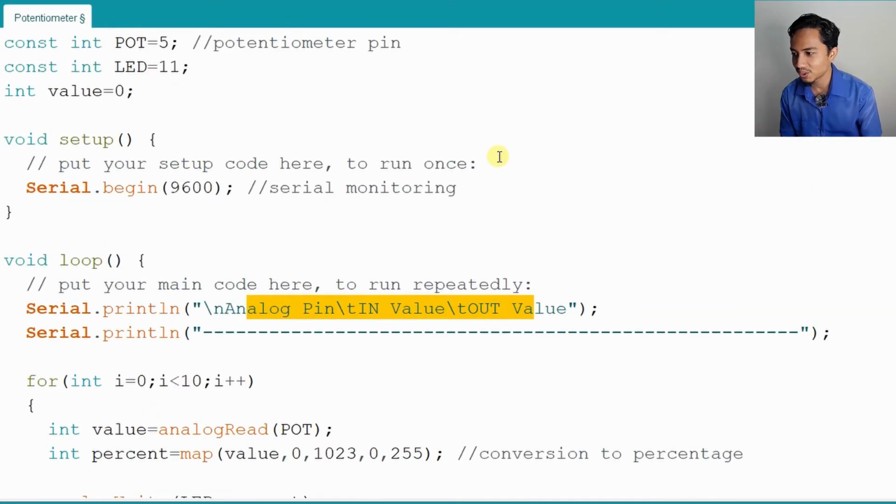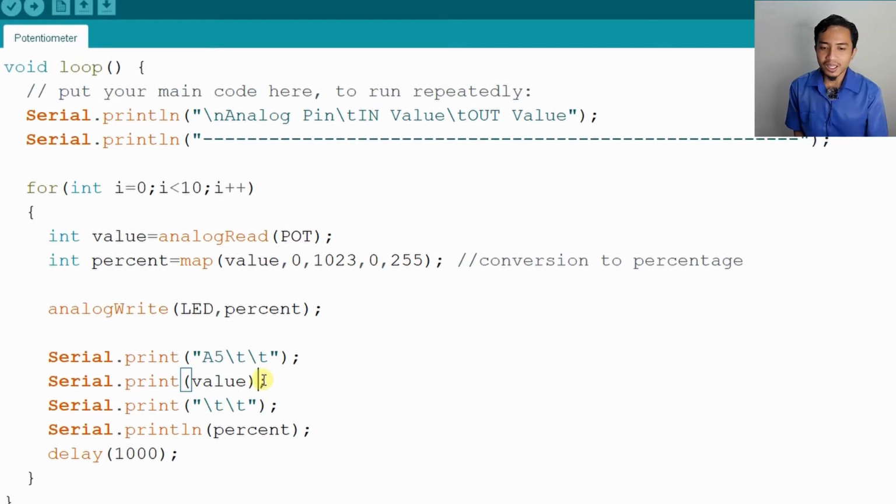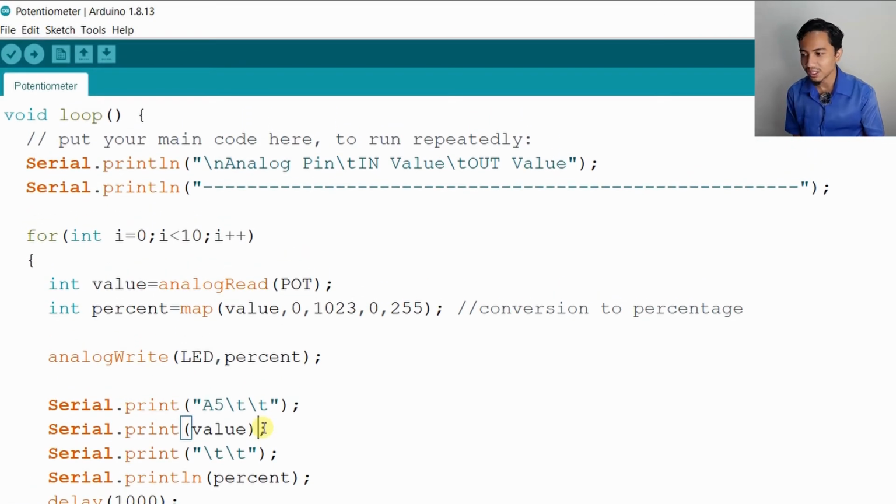And also if you don't want to use the pin number below, you can define the pin LED here. So basically, only these four things are what we add in our code for this kind of coding, which means that we just need to use analogRead and analogWrite to write the LED values with the PWM values. Now we can upload it as usual.